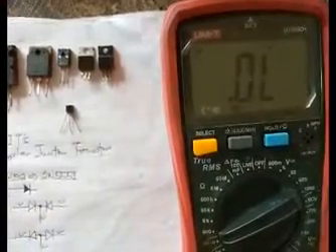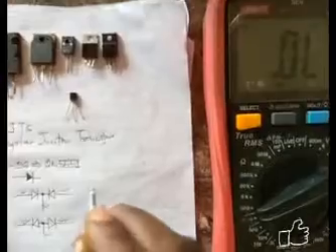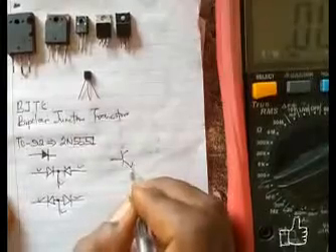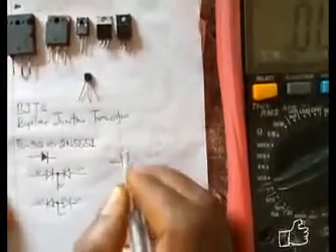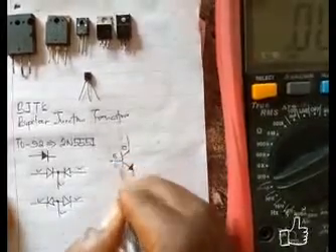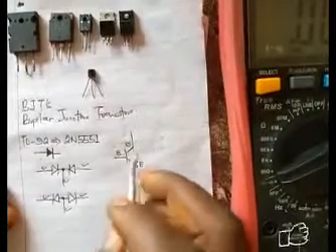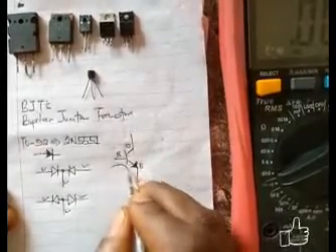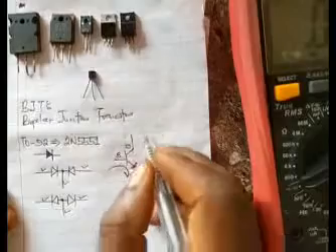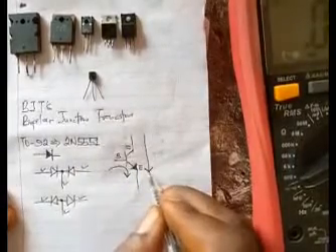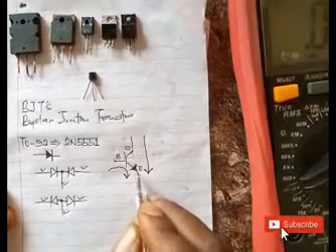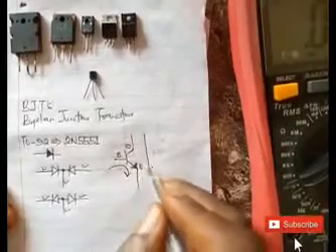And what that switch simply does is this. Now, BJT transistors are current controlled. So let's assume this is my 2N5551. Now, we know this is the circuit symbol of a transistor. This is the collector, this is the base, and this is the emitter. Now, if a current flows from base to emitter, more current will flow from collector to emitter. It simply tells us that this base emitter current is what would make this transistor switch on.